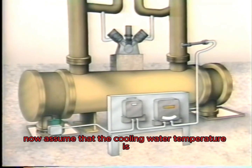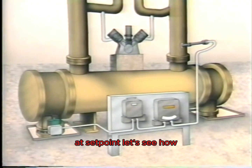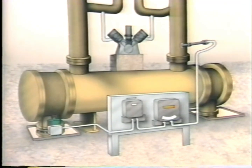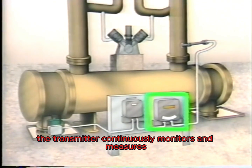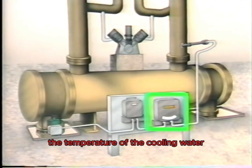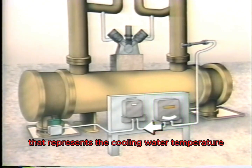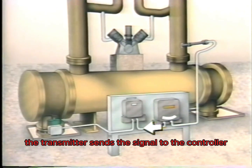Now, assume that the cooling water temperature is at set point. Let's see how the control system maintains cooling water temperature. The transmitter continuously monitors and measures the temperature of the cooling water and produces a pneumatic signal that represents the cooling water temperature. The transmitter sends the signal to the controller.